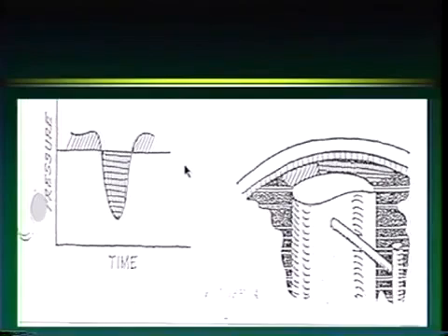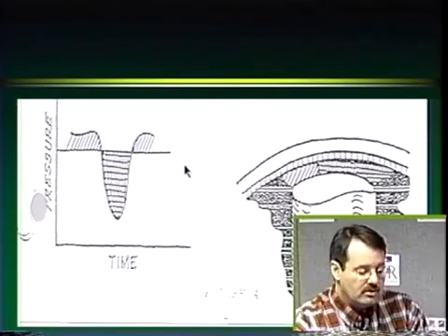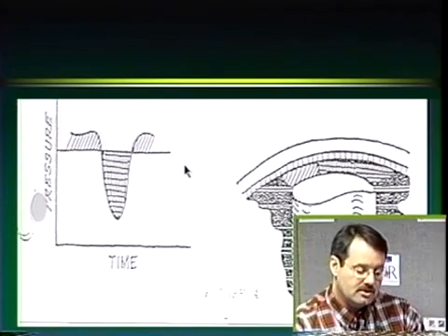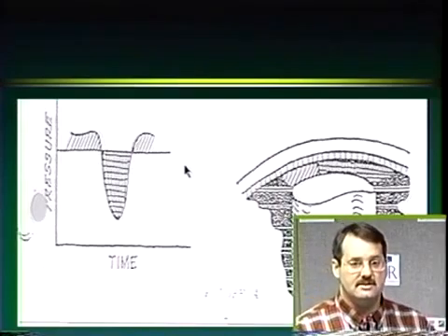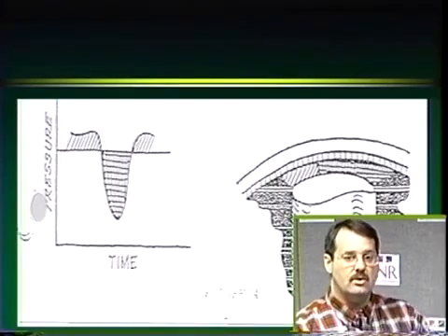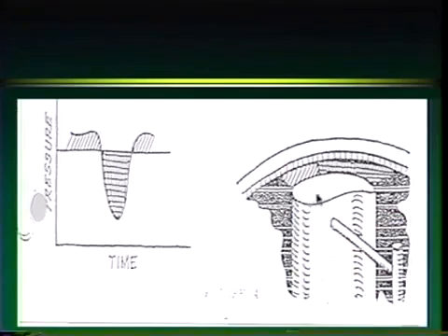Okay, now what I want to do is talk about what that rotor does that was so important. I told you it swirled the pulp around, that's nice, but the rotor does even more than that. That rotor right here is an integral part of keeping this screen from plugging. It prevents the screen from plugging.